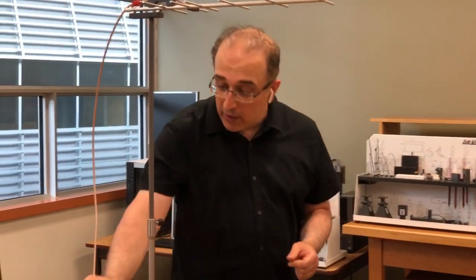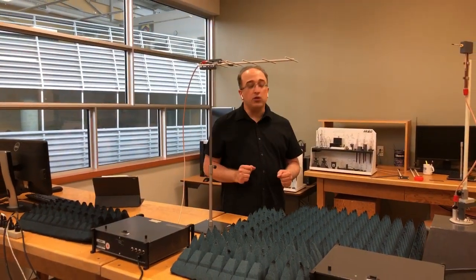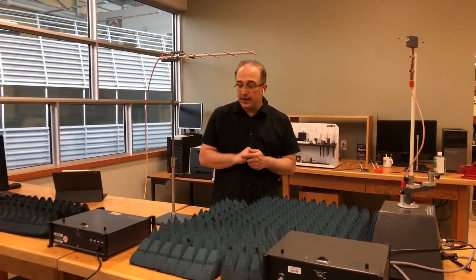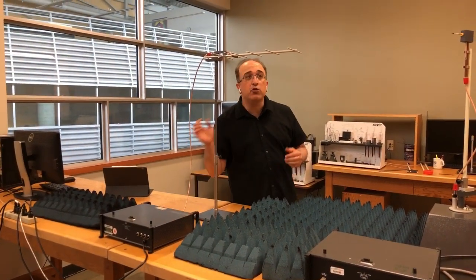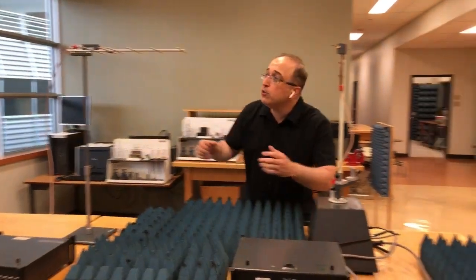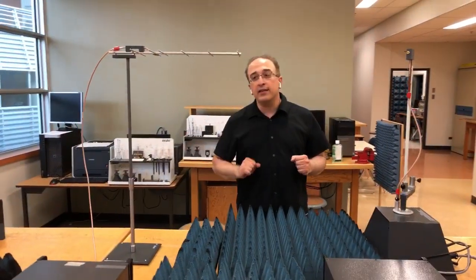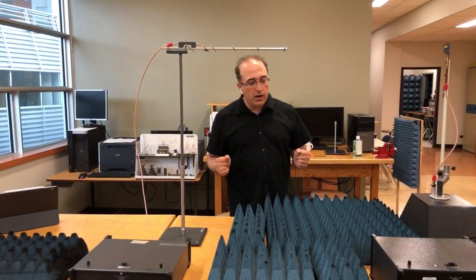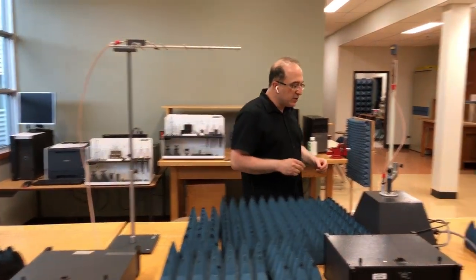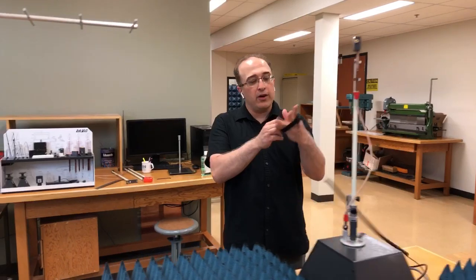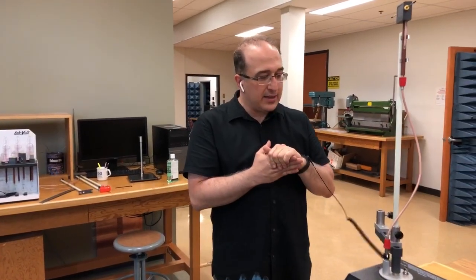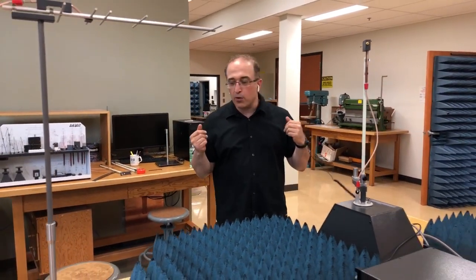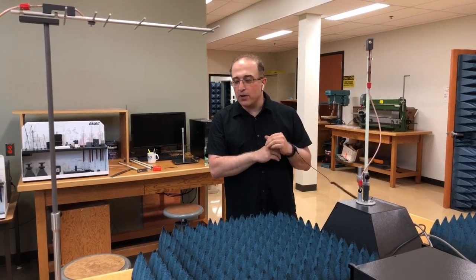electromagnetic energy. So when I turn this on, you see that the system is beeping to let us know that electromagnetic radiation is happening. If I want, for example, to adjust the location of this and I need to look directly into the antenna, it's good that it is off. So that's one consideration. The other thing that you need to be very careful about when you are using this RF equipment is to wear this wristband. This essentially makes sure that the system is safe against electrostatic discharge.